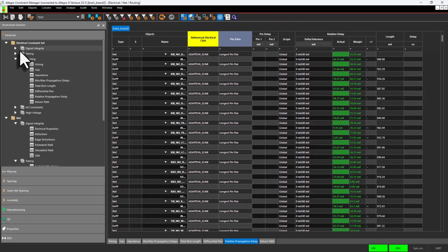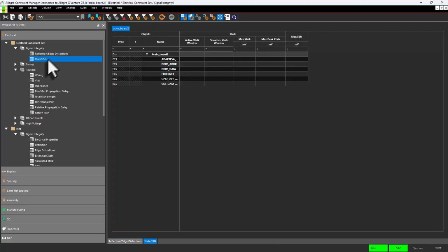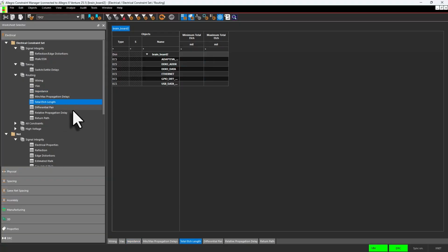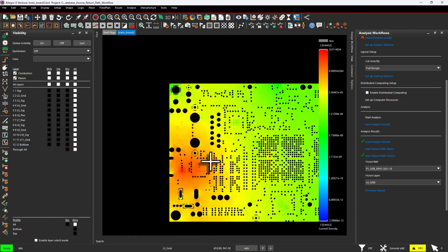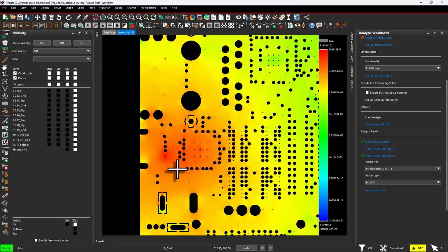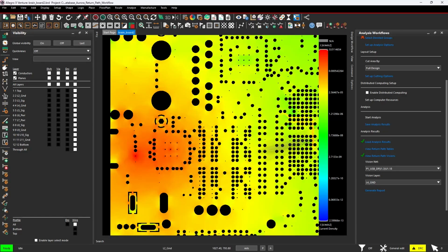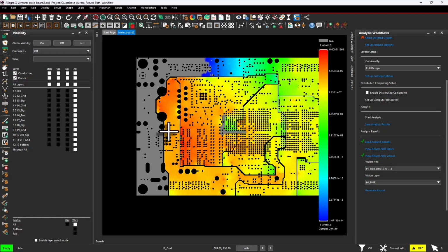So what's the fix? The fix is to treat length matching as one tool, not the whole toolbox. Check your impedance continuity, manage your return paths, get your terminations right, and verify that your differential pairs are balanced. Length matching done in isolation will not save your board from EMC testing. Passing the design rule check is a starting point, not the finish line. The EMC test chamber and the receiver pins on your chips care about the electromagnetic waves, not the PCB design constraints. Manage the electromagnetic waves and fields, and the rest of the board will take care of itself.